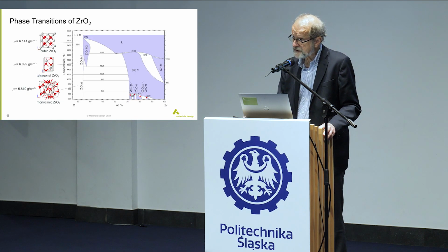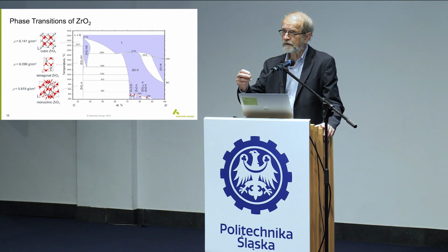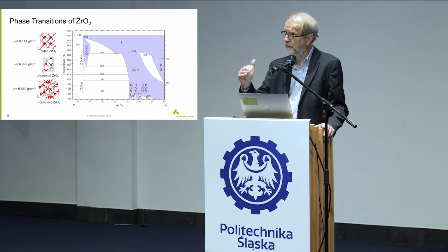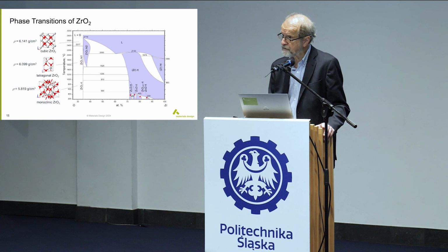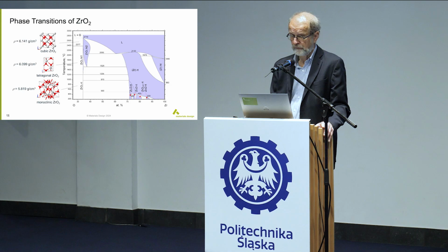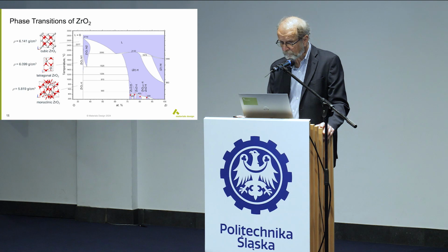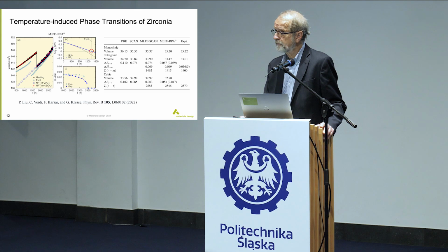Well, to some extent we can get them directly from ab initio calculations. So in the case of zirconium oxidation, you're forming the thermodynamically stable phase, monoclinic ZrO2. At a temperature of 1200 C, it goes through a phase transition to a tetragonal structure and eventually to a cubic structure, before it disintegrates or melts, if you want. Can we predict that? The answer is yes.